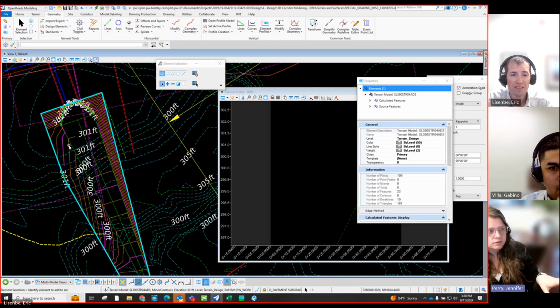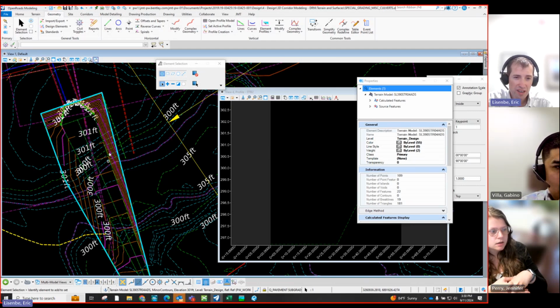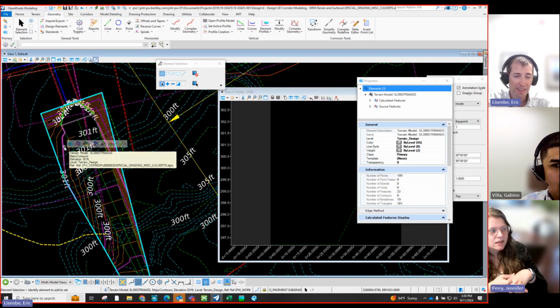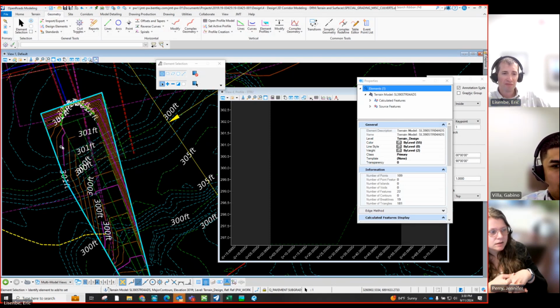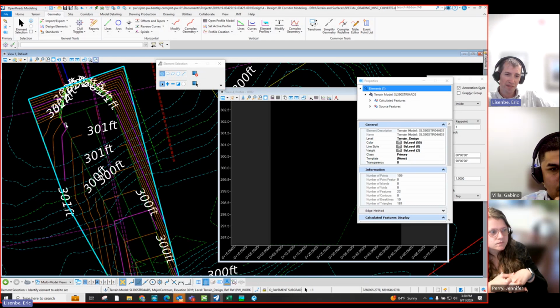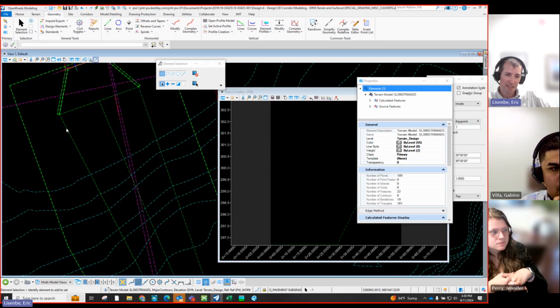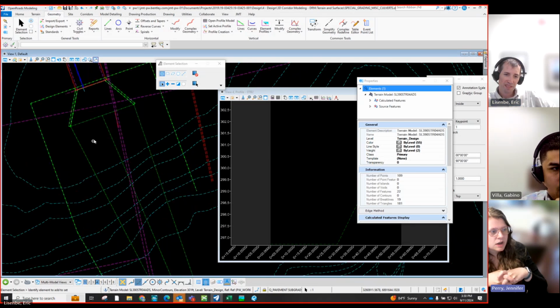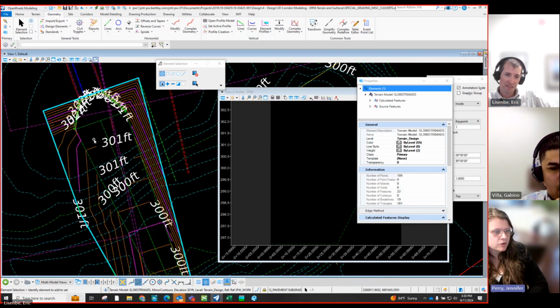those contour lines, because you do them by constant elevation. So you're able to spit this out and then build another terrain after modifying these. I'd be interested in that, because then you just build it from elements. So you would take this out, smooth it however you want, and then rebuild it off those as break lines or as contours. So you just use this as a reference point.